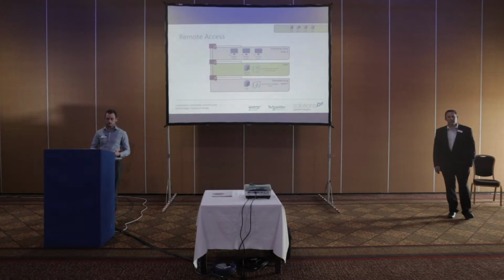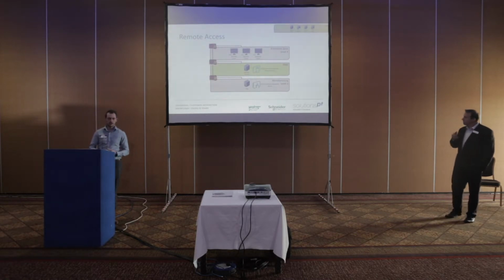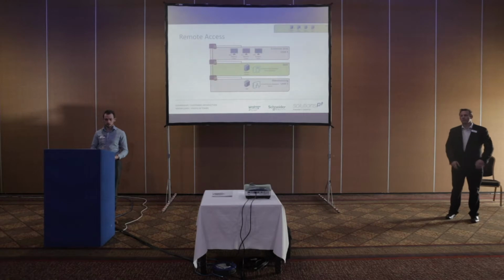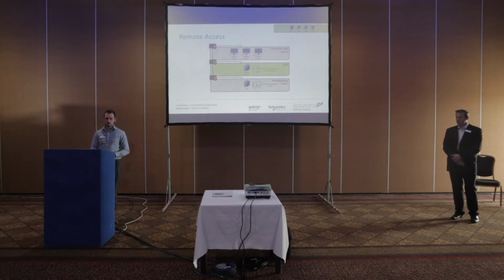So one of the products that has come out on the market in the last few years is something called In-Touch Access Anywhere. So what this does is it allows you to get access to your SCADA system directly on a mobile device. It's full control if you'd like. You can do it in read-only. Obviously, if there's full control, then there's things out there that you might not want people to be accessing, and there has to be the right security protocols in place from a PLC layer to accommodate that.